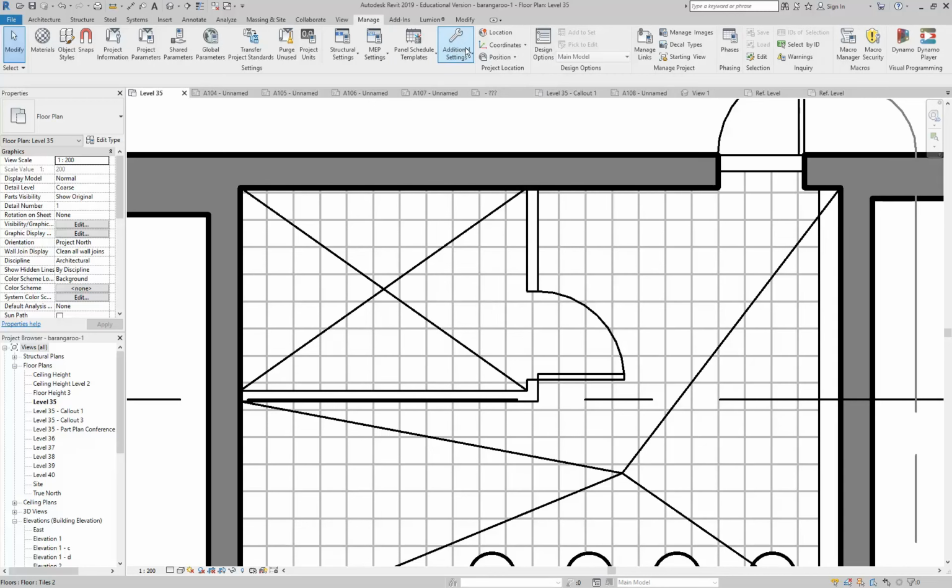So just to go back to AutoCAD, you can make plot style tables. That's often a good way of doing your line weights. If you've got to do a few, you can make a plot style table for each different scale. That works pretty well. Otherwise, you end up having to make different layers for every scale, which is tedious, or set the line weights to your layers every time you need a different scale, which is a really slow way. Yeah, we didn't really learn that.